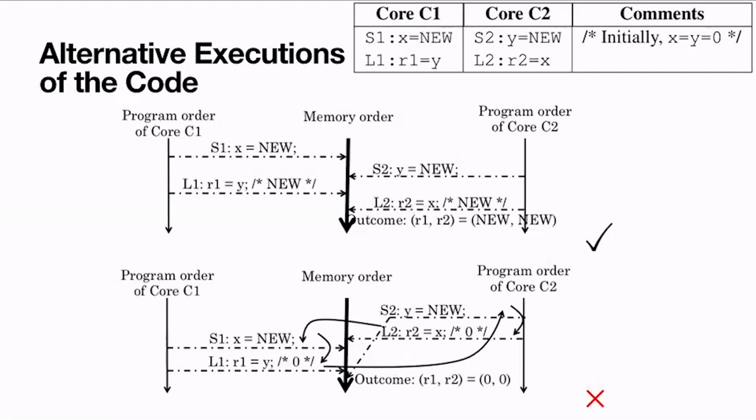So in other words, if my system is supporting sequential consistency, as a programmer, I can safely assume that this system is not going to generate 0, 0. I'll reason out only the remaining things, and accordingly write the rest of my code. Once this is there, the hardware system designer also knows that it is a sequentially consistent design, so he should not reorder any of these instructions. Sequential consistency is easy to implement, but most of the optimizations we considered at the hardware level cannot be applicable here. We have to disable most of the things.